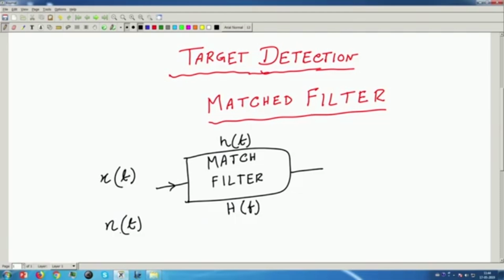For noise-type random signals we cannot define power, but if we know various sample values, from that we can find the correlation function, and from that there is the Wiener-Khinchin theorem by which we can find its power spectral density.